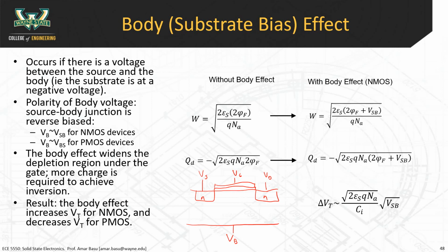And that's what's typically done in an NMOS type device. In a circuit, you'll often see something like this, where the NMOS device is, the source is tied to ground, and then this body will also be tied to ground. And this is the body terminal that they talk about in the transistor.